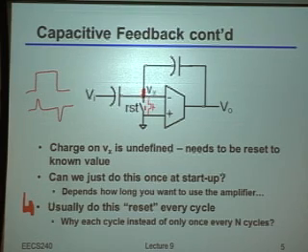Systematic, what do you mean by that? Yeah, it's the same every time. So in other words, it looks like just a DC offset, right? Because every time I use it, it's always the same error. And so if I can just estimate what that DC effect is, or really what that repeated effect on every single sample is, I can basically just knock it out, right? So in other words, it just turns out that oftentimes if you have to create an error, you'd prefer to just make that error sit down at DC so that it's really easy to figure out what the error is and just knock it off in the first place, okay?